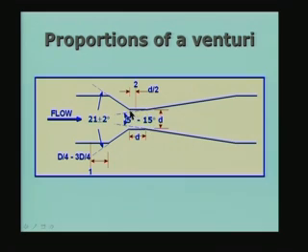As I mentioned, there is a landing which is equal to the diameter of the section here, and the second tap is positioned at d by 2. D by 2 is in the center of this flat portion, and the upstream tap is anywhere between d by 4 and 3d by 4, where d is the pipe diameter, from the start of the converging section. Just before the converging section starts, you can have it anywhere between d by 4 and 3d by 4, as is indicated here. These are the proportions for a standard Venturi, again ASME specification. So, the flow is taking place from this side.